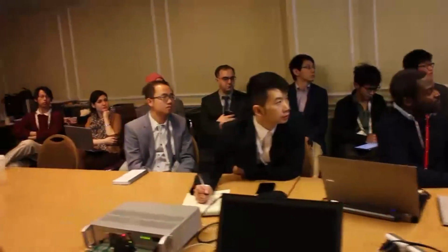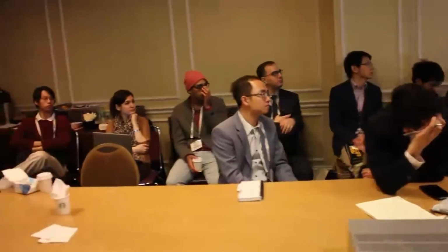Now you say, why are you doing such a crazy thing, Dr. Chuk? Well, because I obviously want to have two complementary switches on input, which are rated at input voltage. You know it, right? And then if I somehow can split this capacitance like in a Chuk converter into two capacitors, voila, here's my isolated Chuk-buck, right? And it has a step-down characteristic, D, and no input inductor, right?